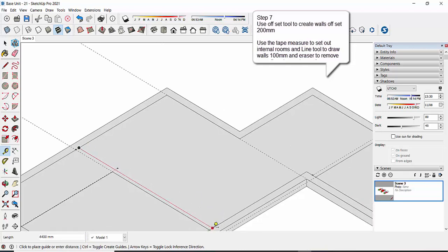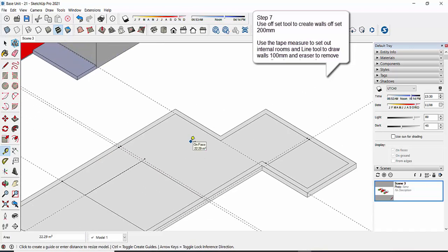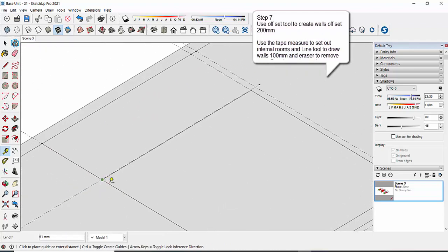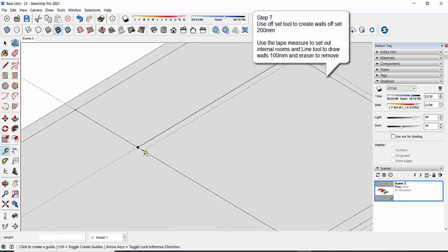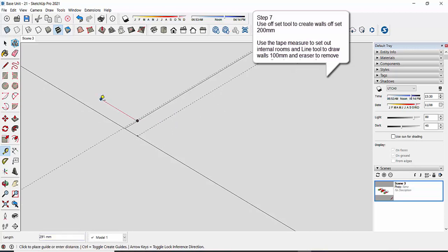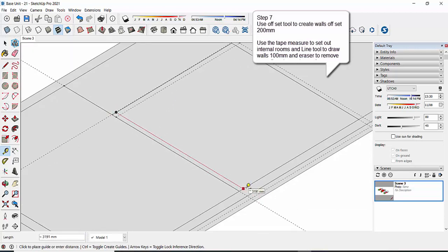And so consequently what happens is, what SketchUp enables us to do, you can see how the guidelines are actually defined. So we have the green line. If it stays in green, that means it's completely parallel to where it should be. If it changes color and goes to black, then you know you're actually not running parallel. So let's come along 100 millimeters. Let's draw a line back.